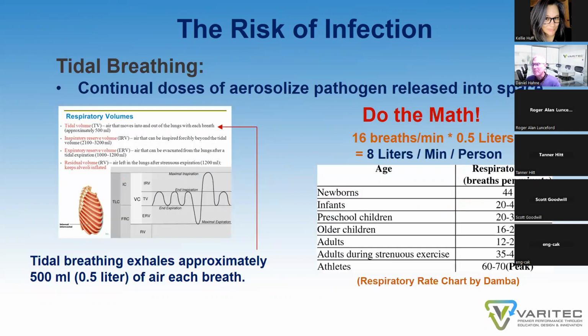So I did the math with Dr. Ho's findings and ran the calculations. The average volume of air released by an adult is approximately half a liter with each breath. And the average adult person has roughly 16 breaths per minute. So every minute, any adult within a space working away at a laptop or working on some papers or whatever at a desk will emit 8 liters of air, potentially, if they are sick, with virally laden small droplets per minute. 8 liters of air per minute.